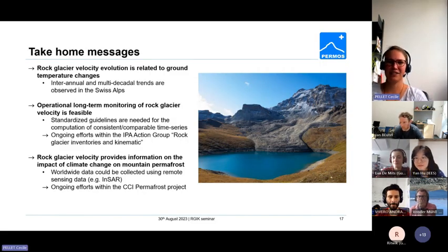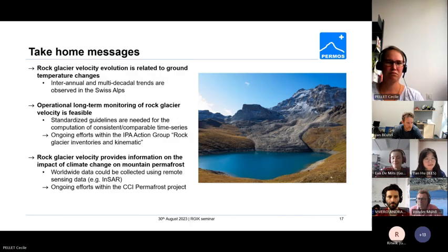Yeah, that's a good question. It really depends why you're replacing your point. Sometimes it's because the boulder is simply rotating on itself, and then maybe you cannot measure it anymore. In this case you would try to look for a boulder very near that probably doesn't do that, or even on the same boulder but behind. But in the case of the front, which is actually most often the case, what we usually do is we go a bit further back to avoid exactly what you said, to have this replacement point fall after 2 years. So that's not very useful.